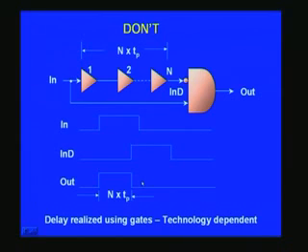In the traditional way which designers normally do, which is an erroneous design practice, you put different buffers in order to achieve n times propagation delay. For example, TP is the propagation delay for each of these buffers. So finally you have a total delay of n into TP, and that is at this point. This is inverted here and fed into the gate, and the input is also fed to this gate with a view to get the final output, a rising positive pulse, from the two inputs that we have here. And this input is basically from, as I said, a push button switch.